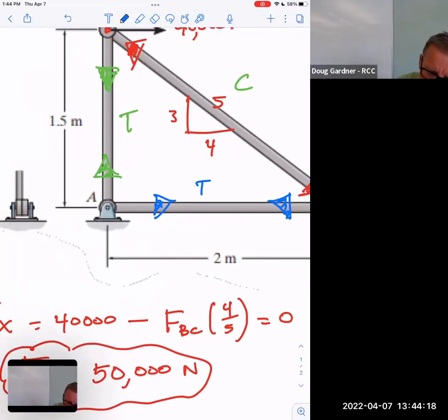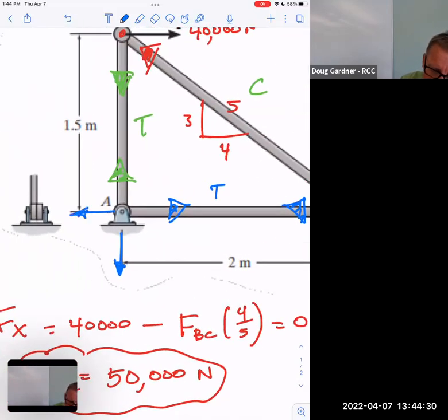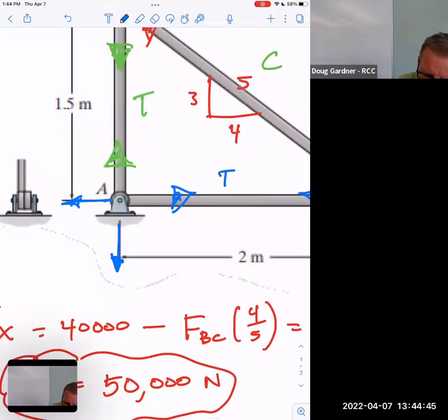And over here, notice it's got green going up, which means this is actually going to have to hold that to the ground. Isn't that interesting? And then you've got that A, B pulling to the right, which means this is going to have to pull back to the left. So that really is required to have two different forces on it. So you see why he put the connections on there, even though we aren't really having to pay any attention to that. Also, with these bolts down here, if you picture a bolt going down into whatever that goes into, does it make sense that if that was being pulled on in some way, those bolts could just slice right off like scissors? Again, that's shear, perpendicular, or parallel to the cut, so to speak.